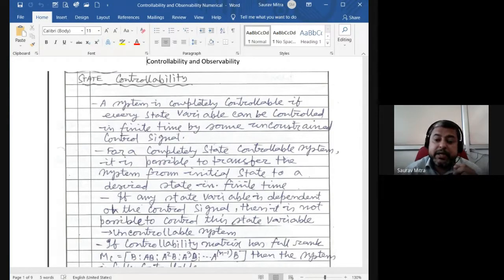Then I ask you, x(t) is the unit step. Find what is the zero input response, what is the zero state response, and what is the overall response. So one numerical from the book of B.P. Lathi, I will upload it today. You have done that numerical. So the same thing we are doing here also, but not by direct method of solution, but by state variable method of solution. So whenever there is a system, there are two responses.